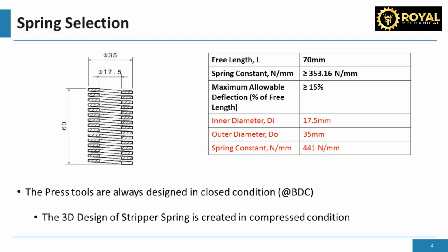The press tools are always designed in the closed condition, which is at the bottom dead center. Hence, the 3D design of the stripper spring is created in a compressed condition. Now let's create the 3D design of the spring. We will design the 3D as per this geometry.